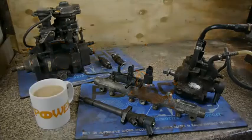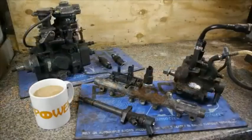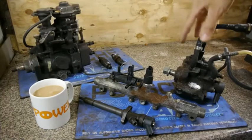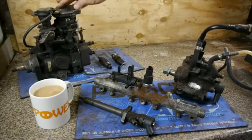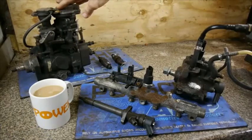Supply fuel system. So we're going to go through the very basics. As modern systems develop, each system varies and improves and changes. So generally speaking there's going to be lots of variation when it comes to these systems, but I'll do my best as I go through. To start with the basics, we have a fuel pump here and a fuel pump here. This is a direct injection, high pressure fuel pump. This is still high pressure, but in comparison to this, a low pressure diesel injection pump.